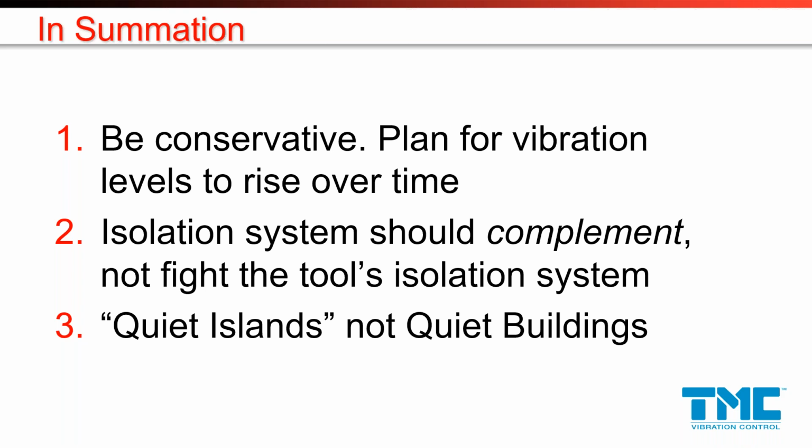Accelerometers use the piezoelectric effect, but velocity sensors use a magnet and a coil, and the magnet and coil moving with respect to each other gives a voltage proportional to velocity. So accelerometers give you a voltage proportional to acceleration. Velocity sensors give you a voltage proportional to velocity. We use velocity sensors simply because they're more sensitive at the low frequencies.